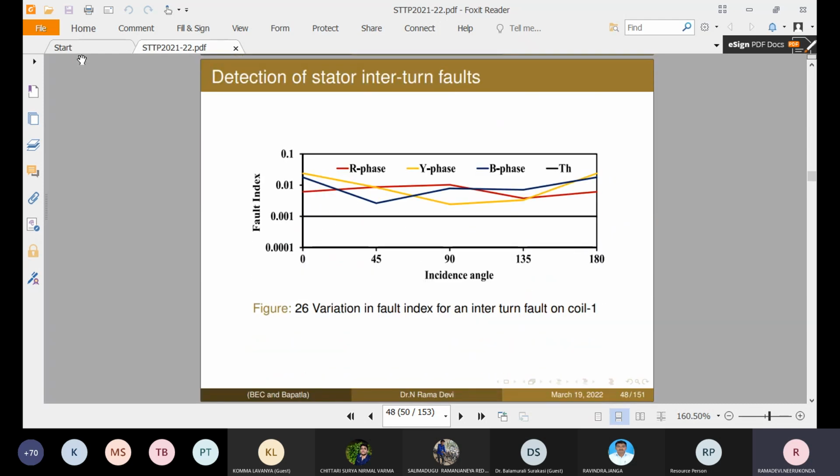Similar studies were done with the help of the simulated model with various switching instants. The switching instant changes over a full cycle, but here the plot indicates a half cycle. Whatever the switching instant changes in the half cycle, the similar impact is in the remaining half cycle, because we consider the fault index value as the absolute value of the peak of the three-phase detail level coefficients.